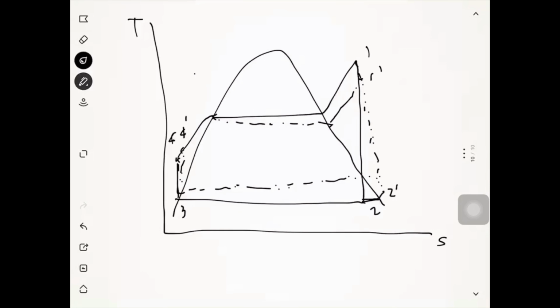But of course, for our analysis, we assume that this is isothermal, because it has no significant effect. But for the isentropic efficiencies, this should be our diagram here, this dotted line. Okay, for example, we have given isentropic efficiencies for our pump, and we have given isentropic efficiencies for our turbine. Okay, so now that is the deviation for the vapor power cycle, actual versus the ideal cycle.